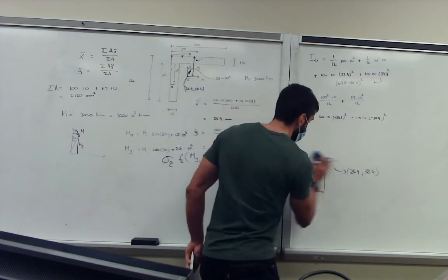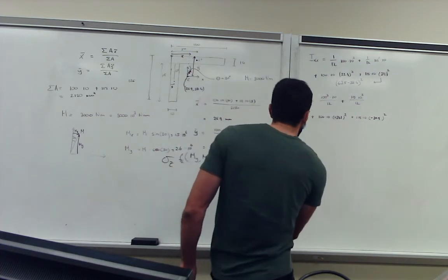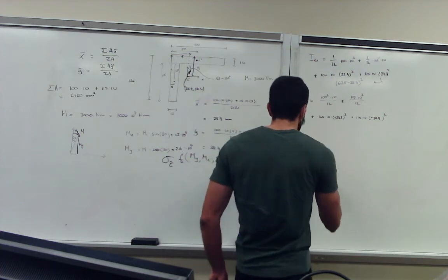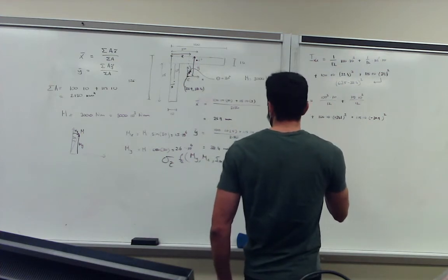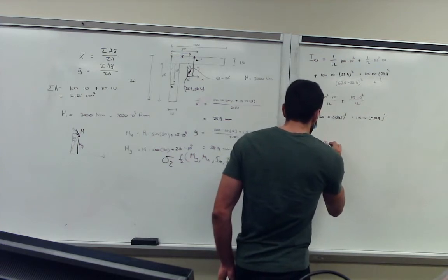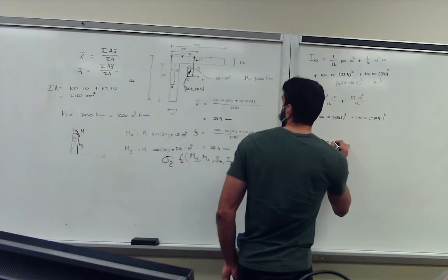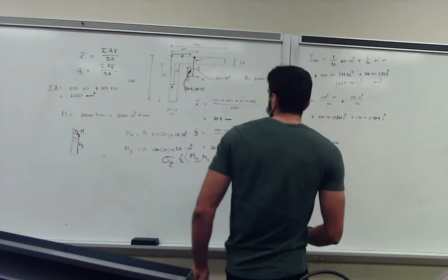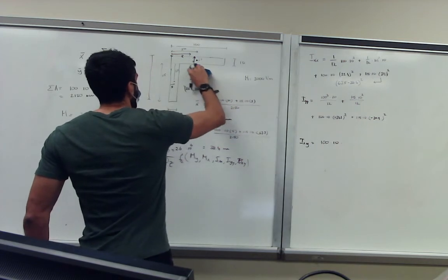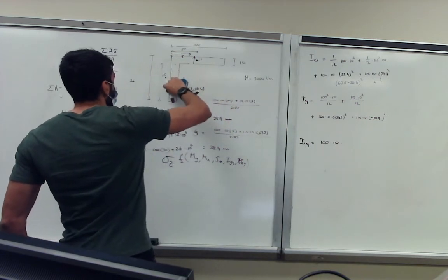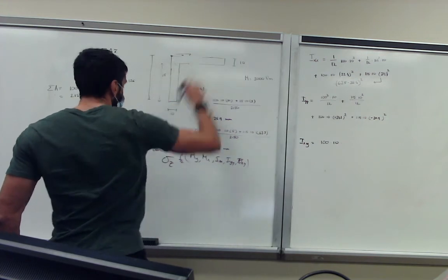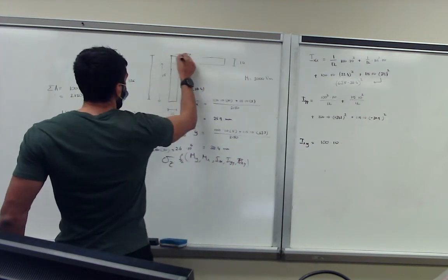And now it becomes important because now you have your IXY. Like I said, that is area times x distance times y distance. Area first is 100 times 10, and we're going to use just the x and y coordinates as I previously wrote down.